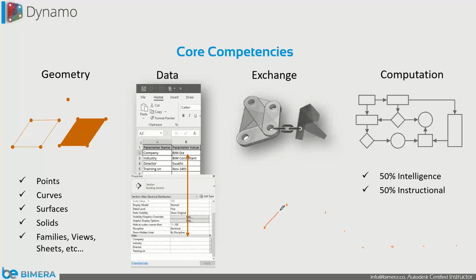If this is a curve, and this is a building, so this is somewhat an edge, and you want to draw cable trays, pipes, or ducts, then what do you do? You will be extracting these points, and you will connect this point with this point, and you will create a duct. From this point to this point, again a duct. From this point to this point, again a duct. One more duct, one more duct, and one more duct.